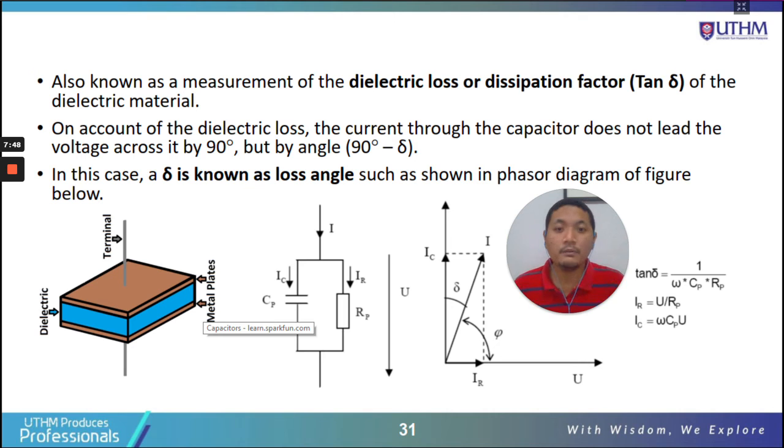However, if the insulation material has some dielectric loss, or leakage current, then if we supply high voltage, let's say 100 volts or 500 volts, with this side grounded, we can measure leakage current flowing through the insulation material.